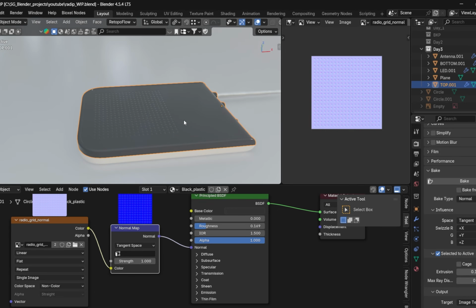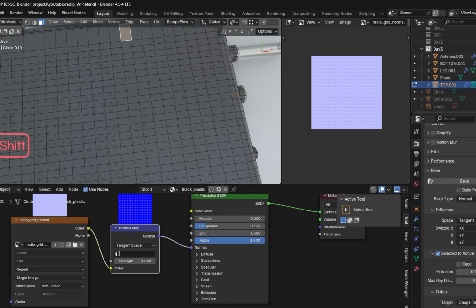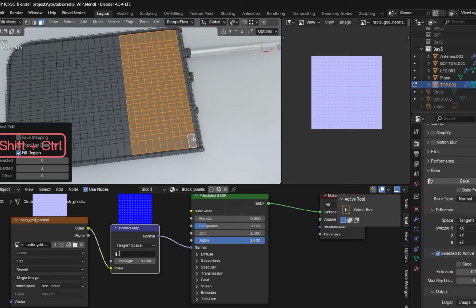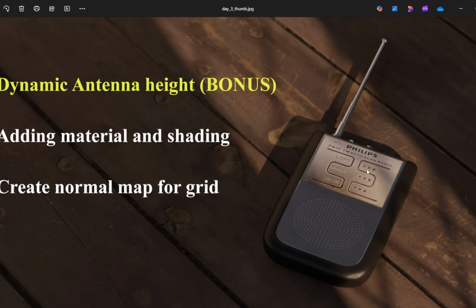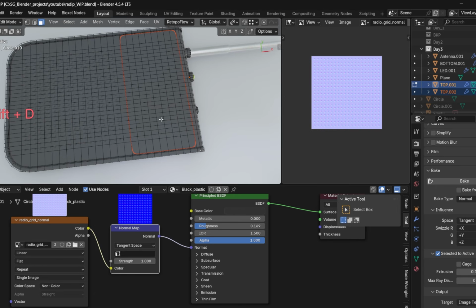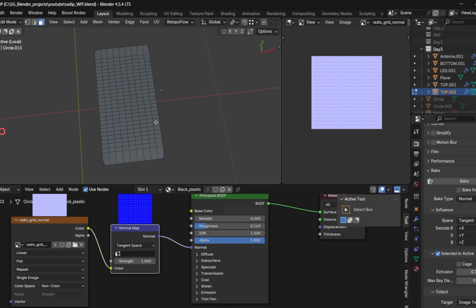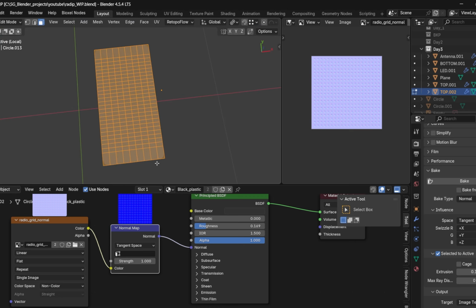Now let's come to this section of our mesh. So remember, for this one, let me select this face where I want that texture to be present. The radio texture, this kind of texture, I have it already downloaded. So instead of doing another UV mapping and making things complex, I will just duplicate this mesh and press P for separate by selection, and for the time being isolate this mesh. And as you can see, its edges have become smooth, right, which we don't want.